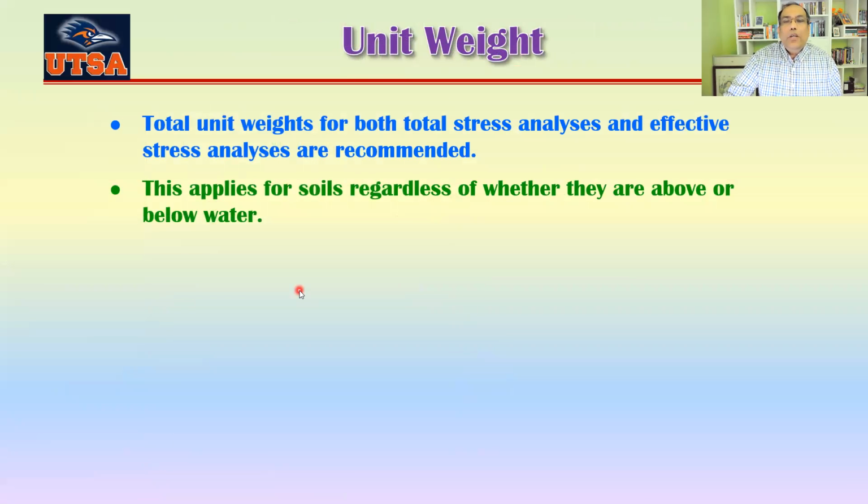Now unit weight of soil is the kind of driving force that's going to take the soil down, okay? Because on the slope there would be a component of the weight of the soil along the slope down there, okay? So the total unit weight is recommended for both total stress analysis and effective stress analysis, okay? So we never use the submerged unit weight, whether this one is underwater or not.